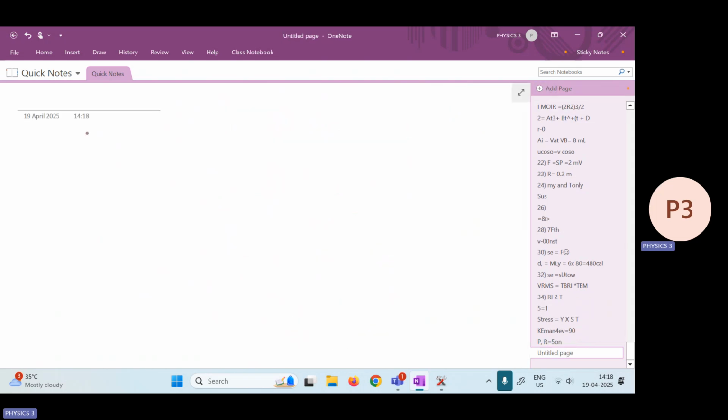The 39th question. In the 39th question, we have been given a PN junction diode not connected to any circuit. Okay, so the potential is the same everywhere is not correct. The p-type side is at higher potential than the n-type side is also not correct, because it is not connected to any circuit. The C option, which says there is an electric field directed from n side to the p side, is absolutely true. So C option is correct in this situation. Okay, we just have to directly learn here.